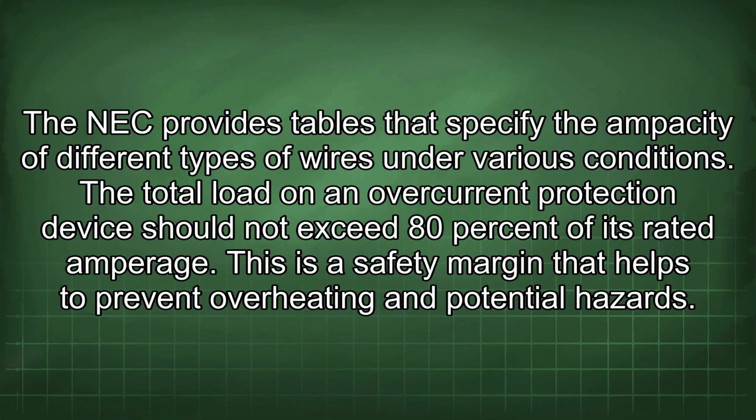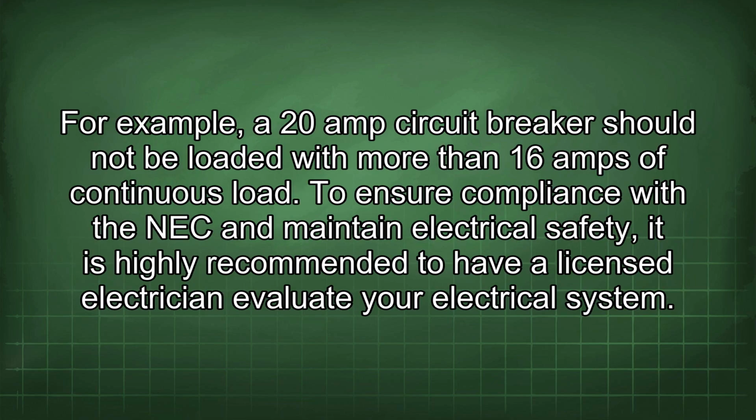This is a safety margin that helps to prevent overheating and potential hazards. For example, a 20 amp circuit breaker should not be loaded with more than 16 amps of continuous load. To ensure compliance with the NEC and maintain electrical safety, it is highly recommended to have a licensed electrician evaluate